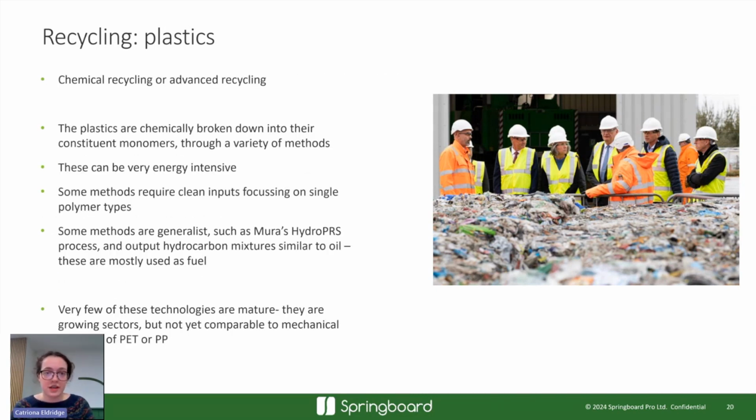Chemical recycling or advanced recycling is a really broad topic. So you've got things like glycolysis, you've got methanolysis, you've got pyrolysis, you've got steam hydrolysis. And what all of these things are aiming to do is use chemistry to get back to a pure product. So with dissolution, what you do is you dissolve your feedstock, having sorted it very carefully, having cleaned it very carefully, and you aim to pull into solution just the polymer you're interested in, and you then re-extract that through a few more chemical steps. So that approach requires a very clean input, and it focuses on a single polymer type, but you do get a single polymer type back out the other end.